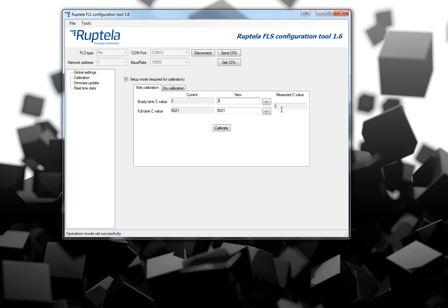Once I start to insert my fuel level sensor in the fuel tube, which is full of diesel, we need to make sure that the fuel sensor is completely immersed in the fuel. To do that, you need to put the fuel sensor in and watch the values. Now I have inserted it inside of the diesel tube, and as we can see, the values are increasing.